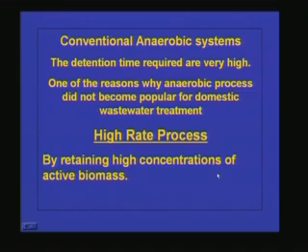So if we can reduce the detention time, definitely the treatment system will become more attractive. The reason is that we have seen that the anaerobic process has many advantages over the aerobic process. The energy requirement is very low, because in an aerobic system we have to aerate the wastewater, we have to supply oxygen externally to meet the oxygen requirement, but in the anaerobic process oxygen is not required at all, because the substrate acts as the electron donor as well as the electron acceptor.